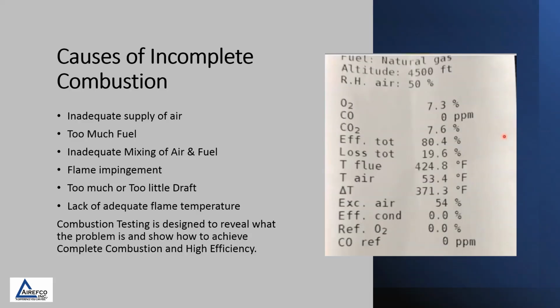The causes of incomplete combustion may include inadequate supply of air, too much fuel being supplied, an inadequate mixing of the air and fuel, flame impingement on the burner, too much or too little draft, and lack of adequate flame temperature. Combustion testing is designed to reveal what the problem is and show how to achieve complete combustion and high efficiency.